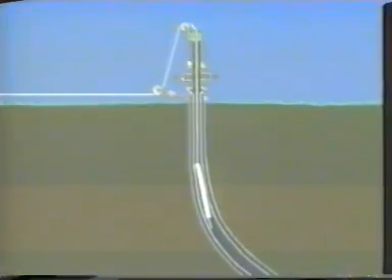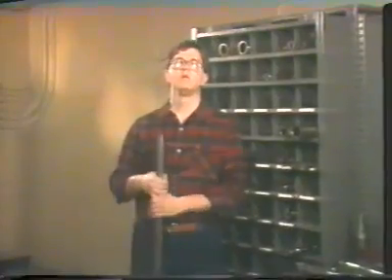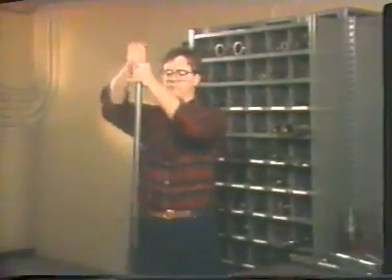Long tool strings must also be somewhat flexible to allow the tools to pass through the tubing, which in many cases is not perfectly straight. Of course, we must be able to perform work with the tool string once we position it in the well at the proper depth. Since we cannot rotate the tool string, and since wireline's small diameter limits the amount we can pull on it, wireline work is accomplished by delivering a series of hammer-like blows, either upward or downward, using the tool string. This is called jarring. And it is delivering this action which is the primary function of the tool string.